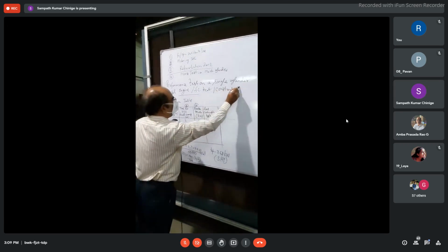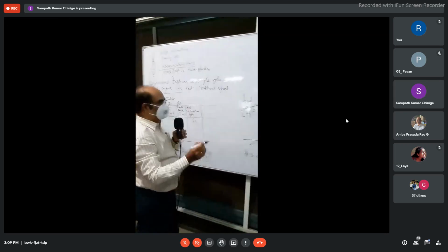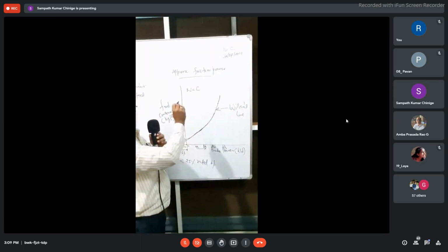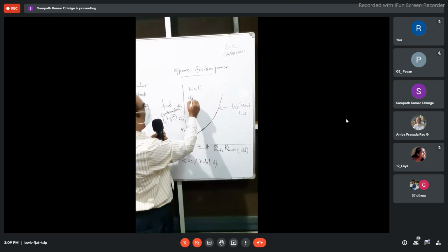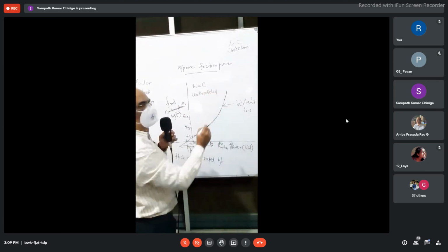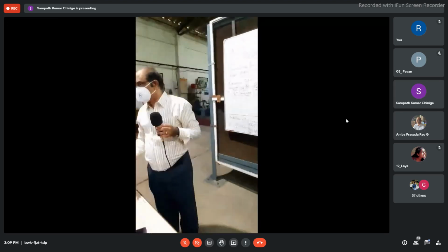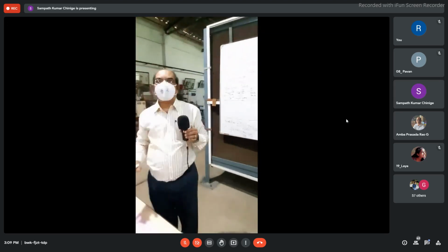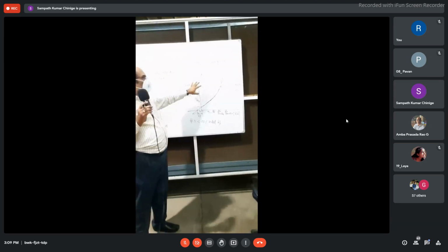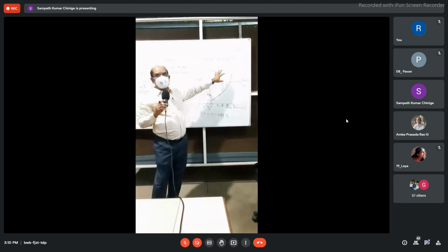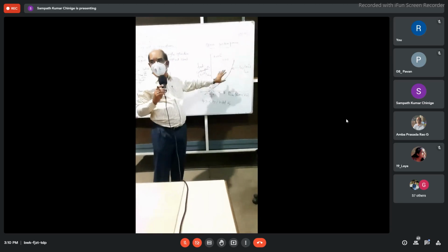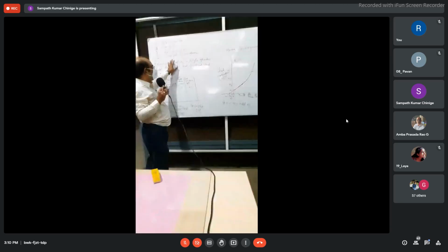This Willans line method holds good only for constant speed operation and mostly for unthrottled engines. We are not throttling the incoming charge of the engine. Diesel engines are known for being unthrottled because we allow the engine to take as much air as possible. Further, the Willans line method is very much suitable for getting the approximate value of the friction power. So this is one method. This we have already drawn, I hope, by calculating the different parameters here.